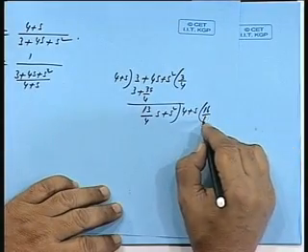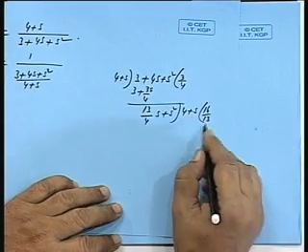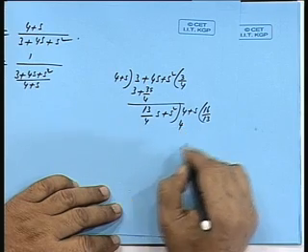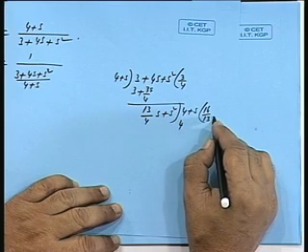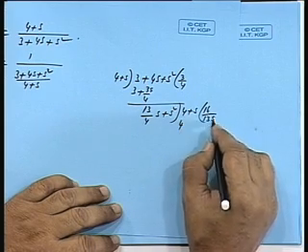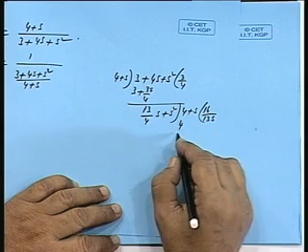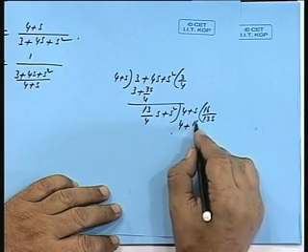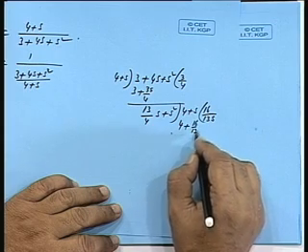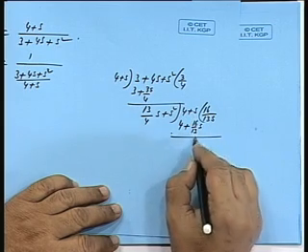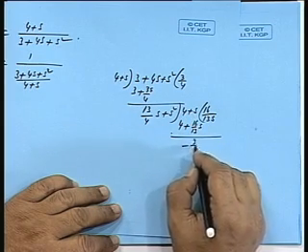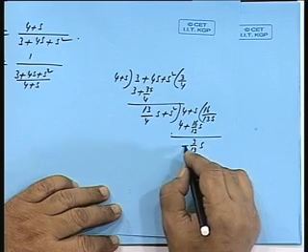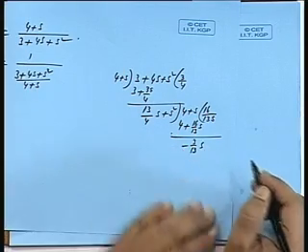16 by 13. Is that all right? That gives me 4, 16 by 13 s in the denominator. So, that gives me 4 plus 16 by 13 s. Now, that gives me minus 3 by 13 s. So, since there is a negative sign, it is not possible to realize by Cauer 2. Cauer 2 does not exist.